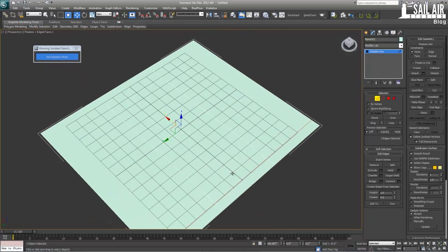Really what I want this to be is 3 feet up. Since the floor is usually 10 feet tall with the ceiling and blah blah blah, I thought 3 feet foundations would be good enough. So you can see that the bottom plate is set at 78, I'm going to assume. See, it pops over 78. So 78 minus 36, which is 3 feet, is 42. Negative 42. And there that is.